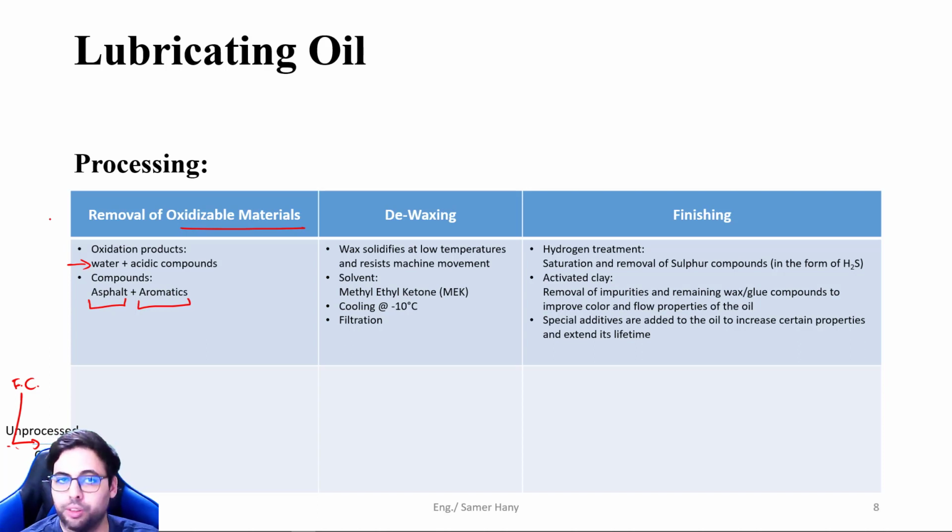First off, the water will not mix with the oil. They are not miscible with each other. They do not dissolve in each other. So it will break the consistency and the homogeneity of the oil layer, and will start decreasing the viscosity. So the oil will not be able to function well to create a viscous layer between the solid parts that are moving in contact with each other.